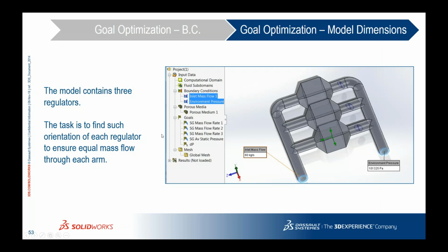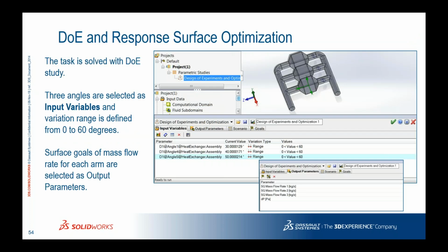So let's talk also about goal optimization with multi-parameters. In this case, I would like to share this exercise. It's an example about the design of experiment inside Flow Simulation. In this case, we are setting up a collector with 3 porous media, 3 filters, and 3 valves. Here you can see also the angle of the valves, and of course an output. So we'd like to achieve, let's say, a very steady flow at the outlet with this flow rate in mind. How to achieve that?